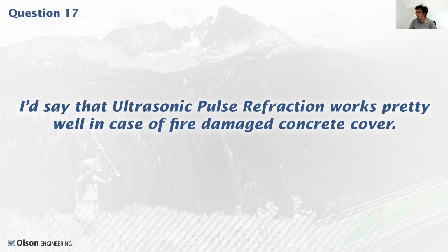Okay. The next one seems to be more of a comment than a question, but he says that I'd say that ultrasonic pulse refraction works pretty well in case of fire damaged concrete cover. Yeah, I could see that working. I haven't spent too much time trying to do refraction on concrete, but what I have seen is it is kind of difficult to resolve what is the refractor.